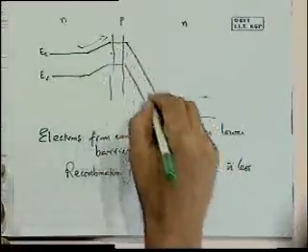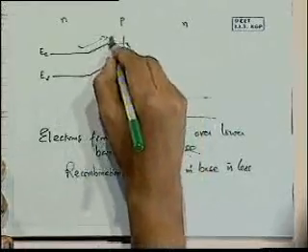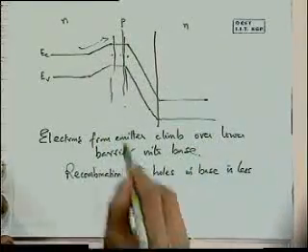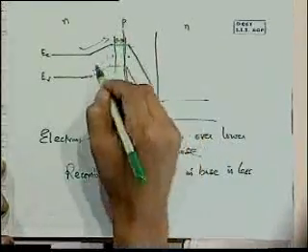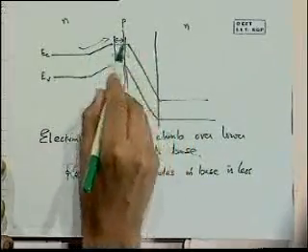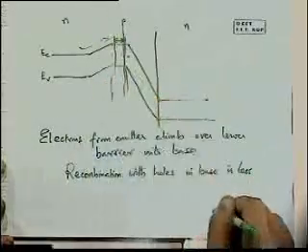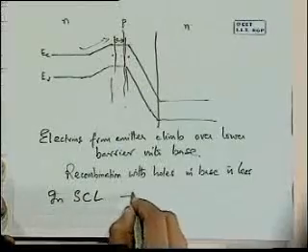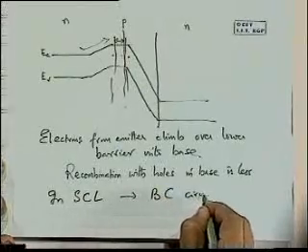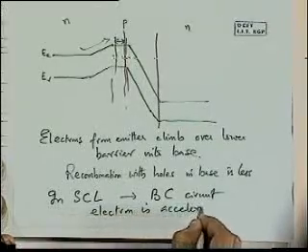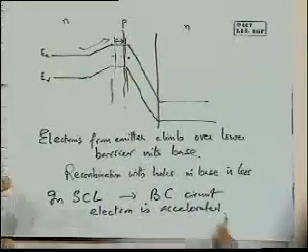And it is this acceleration that is causing the amplification, because here it has to cross the barrier, but once it enters into this depletion region, it's going to experience an acceleration down that. So as long as this is very thin and we don't lose too many to recombination, the electrons that are injected from here will enter into the depletion region here, where there is a very strong acceleration. The gradient is such as to cause the electrons to be accelerated. So in the space charge layer connected with the base collector circuit, the electron is accelerated. Okay? So that's the fundamental basis.